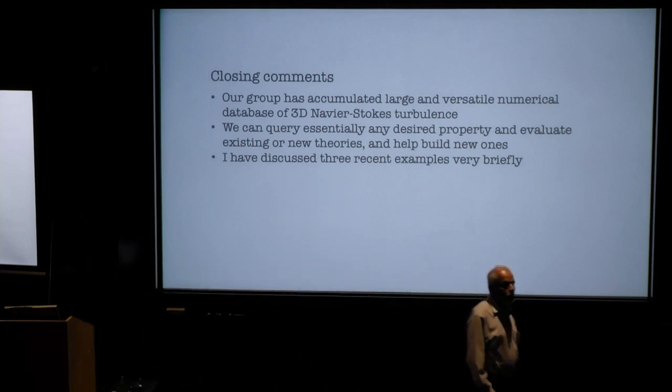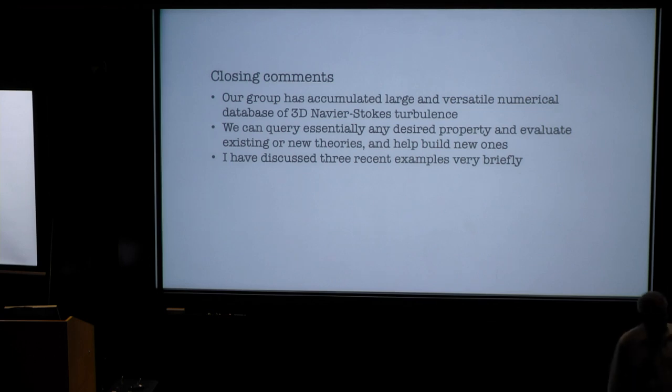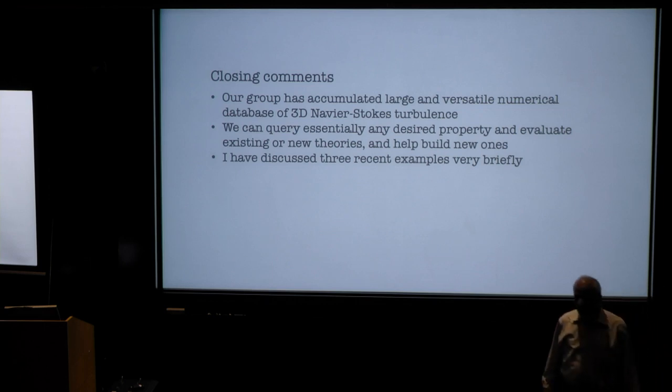In this large database, is any of it at all compressible, or is it all incompressible? Yeah, there is compressible data as well. And there, what we find is, this was the root of the question I was asking this morning. If you separate the flow field into dilatational and divergence-free parts, then you actually find that the divergence-free part really follows pretty much like the standard incompressible case. I mean, one has to be a little bit careful, but okay, qualitatively, my statement is correct. Yeah. Thank you.